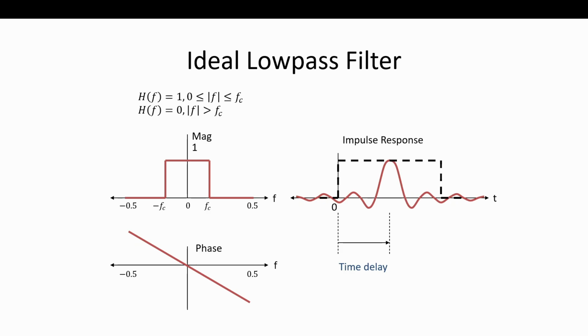Okay, so that's saying, hey, we want this ideally. This is what we have to do. The longer you delay, the better we can get. So doesn't that make sense? When we just talked about, hey, if we want a really tight filter, we need a really long time delay. Well, you can kind of see it. It allows us to include more of those important tails that define that brick wall response that we're trying to get to. Make sense?